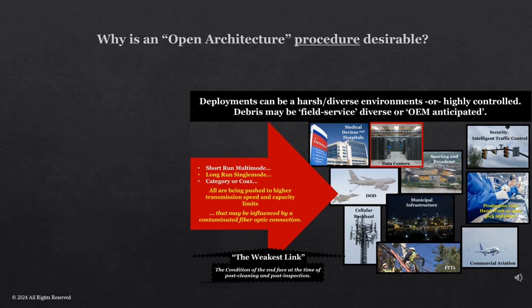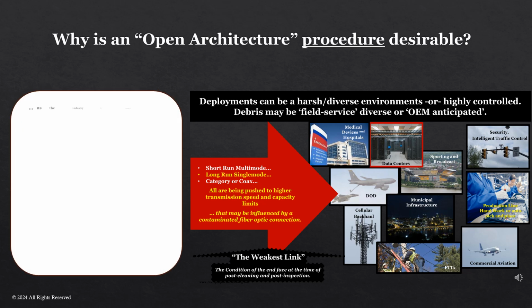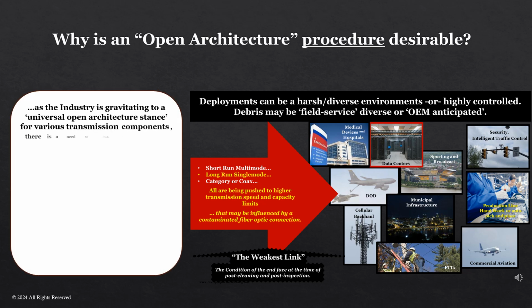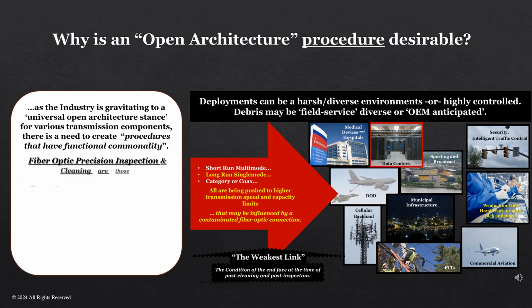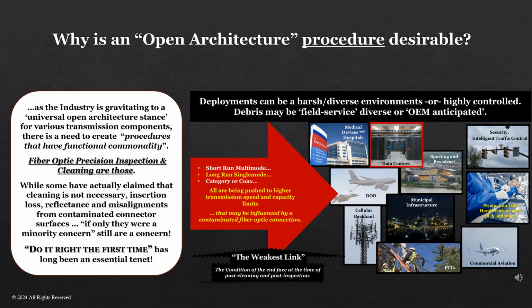As an SCCA competition designer and builder, one of the very first things I learned was do it right the first time. That was after many times of not doing it right the first time. And this included such things as selecting SAE grade 8 bolts and nuts and washers, and occasionally NAS standard bolts, and SAE grade lubricants.